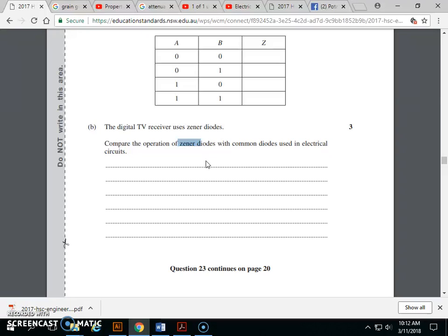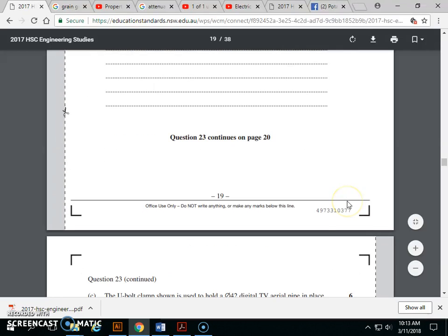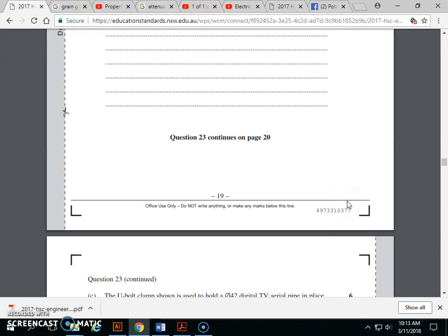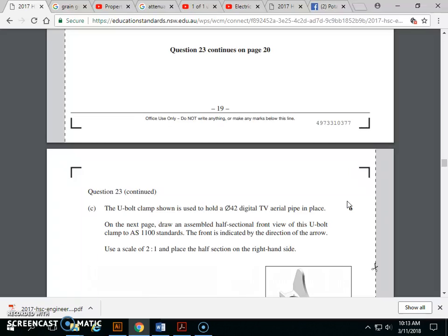Now, what's the effect if you run an AC current through a diode? If we just run an AC current through a diode, what we'll get is a half-wave rectification. Yeah, so we'll just have the bump, bump, bump. That's where we have multiple. We have the four rectifiers.